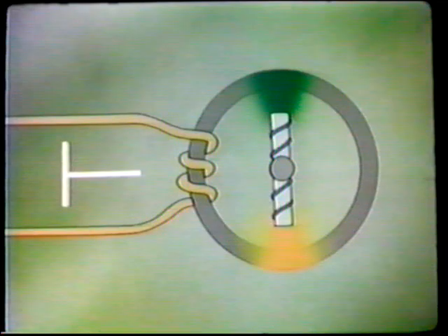The second factor is the design of the generator. A generator's output voltage is determined by the way it's built. The physical arrangement of the conductors inside the stator and the number of conductors are both important design considerations. But these considerations are determined prior to the manufacture of the generator, so a generator's design can't be used to control its output voltage. That leaves us with a third factor, the strength of the field.